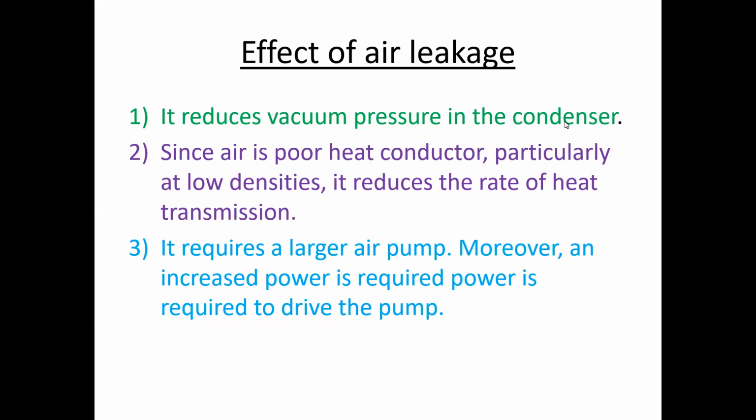First, it reduces the vacuum pressure inside the condenser shell. Second, since air is a poor heat conductor, particularly at low densities, it reduces the rate of heat transmission. So this is another effect of air leakage. What heat transmission? That means the effect of cooling down of steam into water, into the condensate.